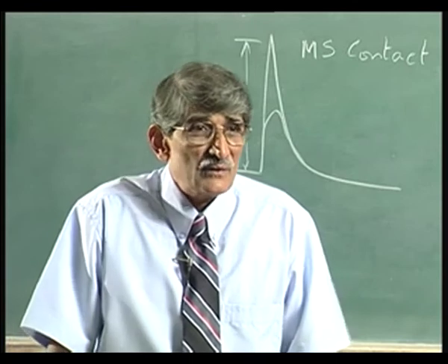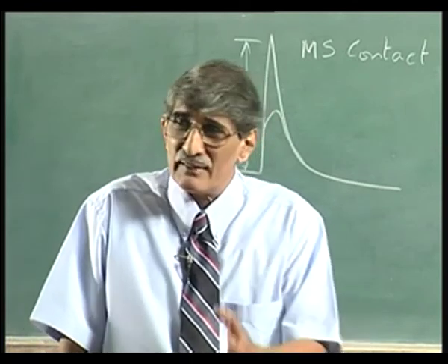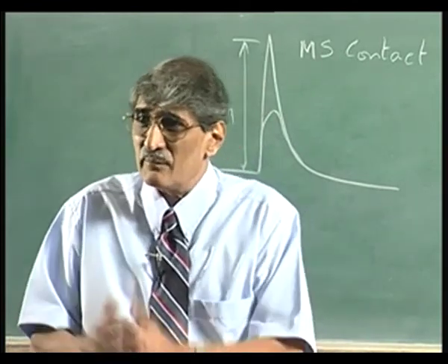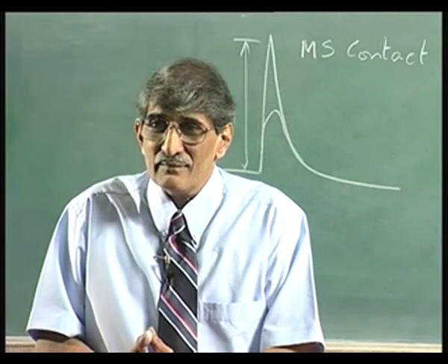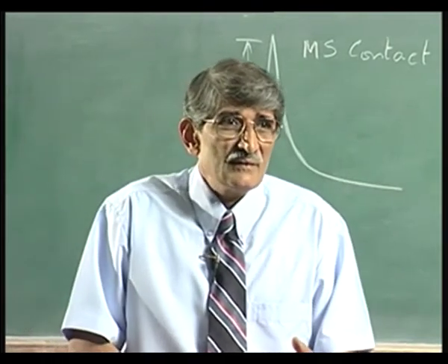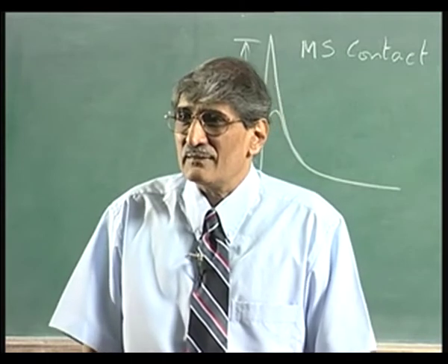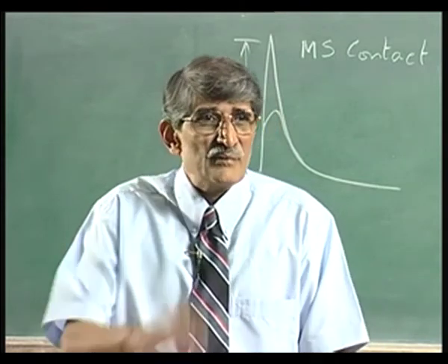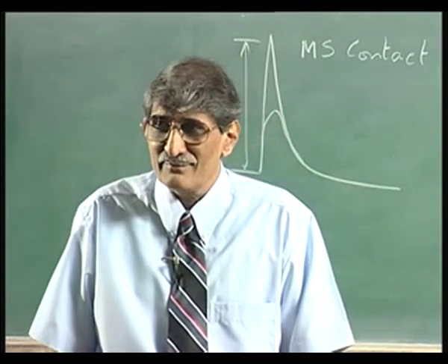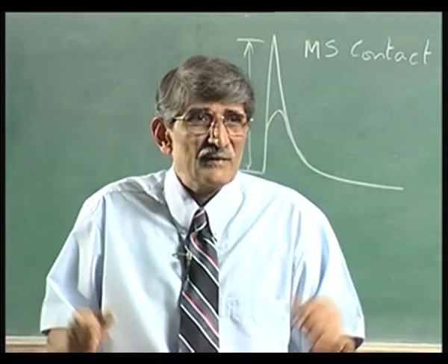Today, you go to gallium nitride, much wider band gap. You go to silicon carbide, the worry for the technologist is making a good ohmic contact. Schottky barrier, you just put a metal, make a Schottky barrier, absolutely no problem. The ohmic contact is a problem.